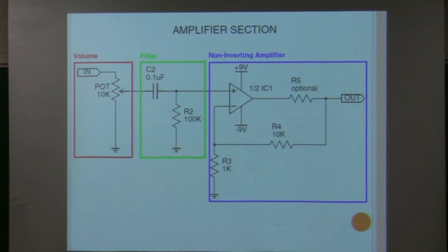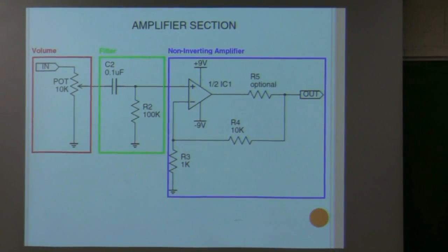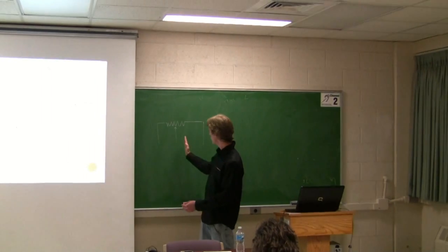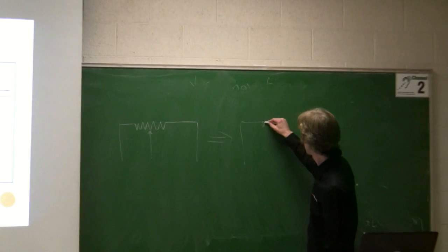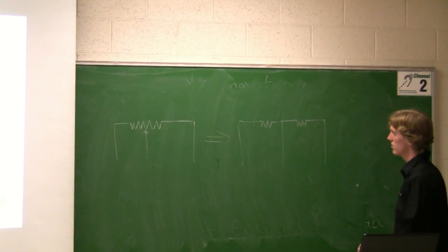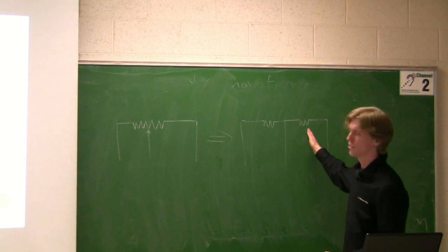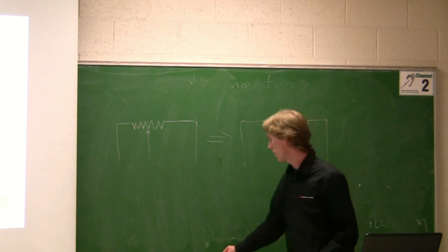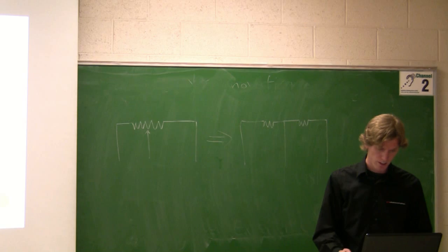So the general idea with a potentiometer is that you have a certain resistance, and then you have this little wiper here, which you can move back and forth. This is equivalent to pretty much 2 resistors in series. So you can adjust the ratio of these 2 resistors, and you get an adjustable voltage divider, which is essentially used to control the voltage that's going into your amplifier.